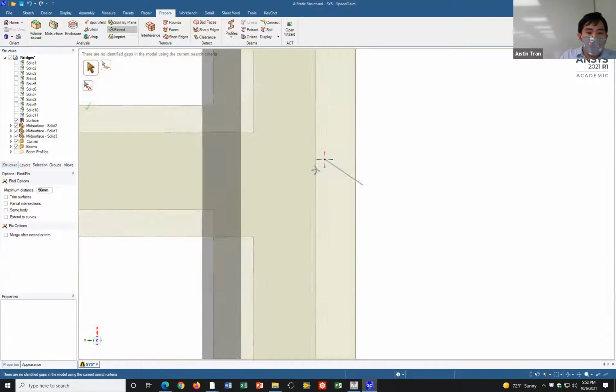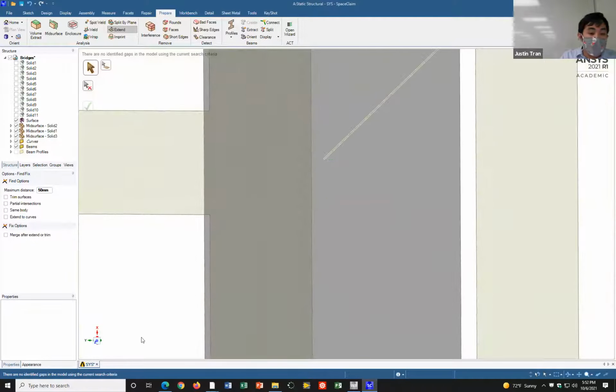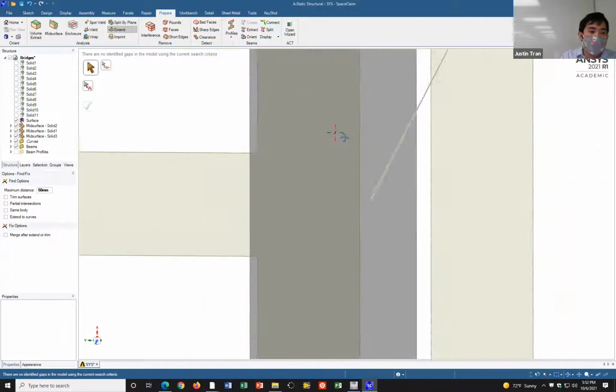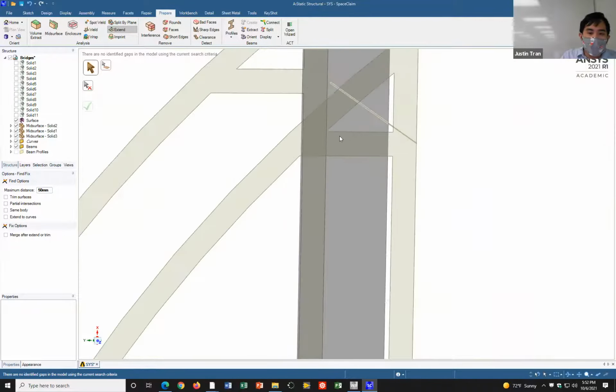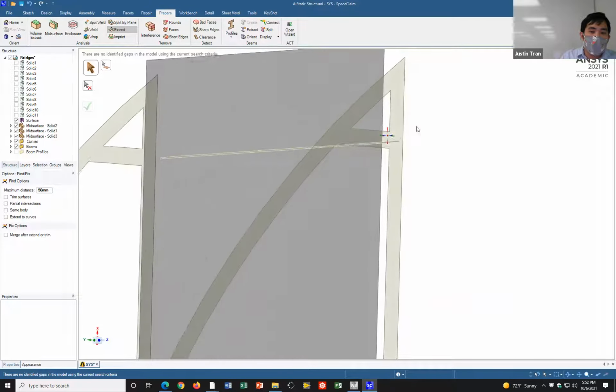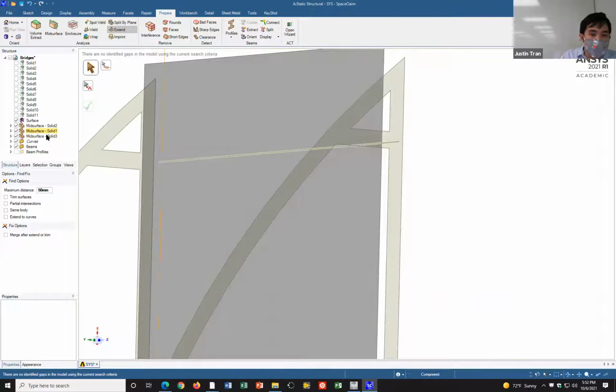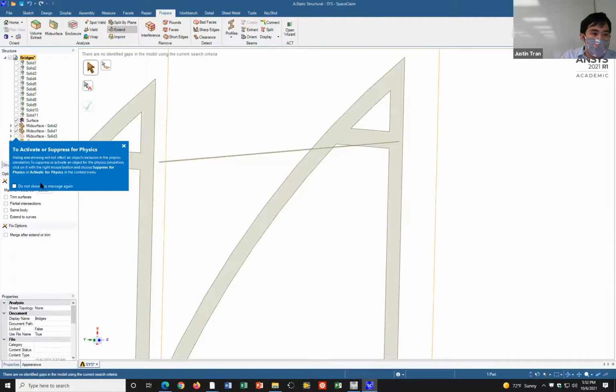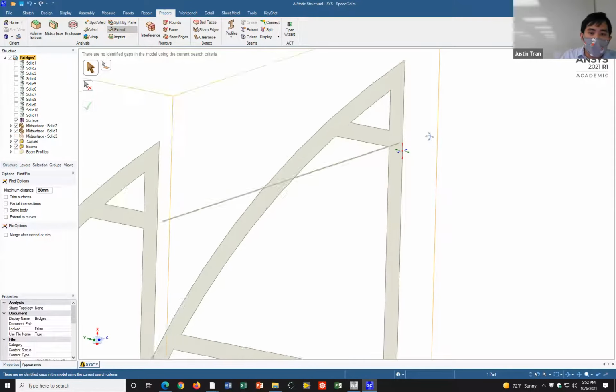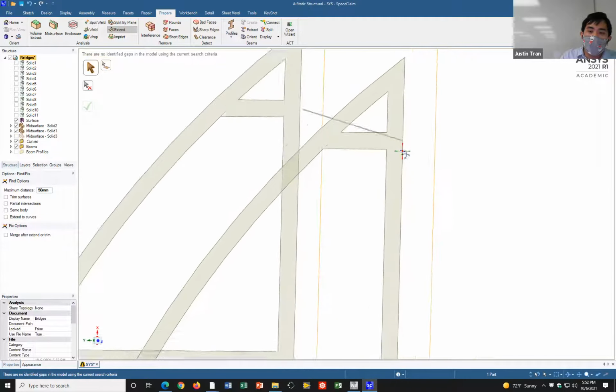And so we're going to manually move this beam in the Y direction such that it actually starts to intersect with the bridge. And actually, to make this a little bit easier, I'm going to go ahead and hide the road. Okay. And so your road, I think, should be the third one here. I'm going to uncheck this just so that we can hide it for a second, to make it easier for us to perform this action. Okay.